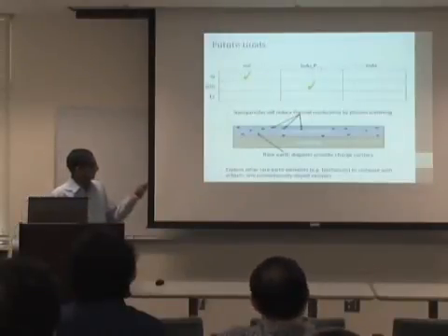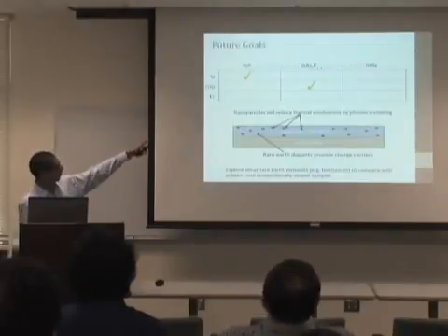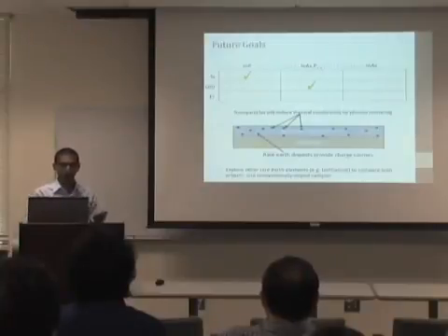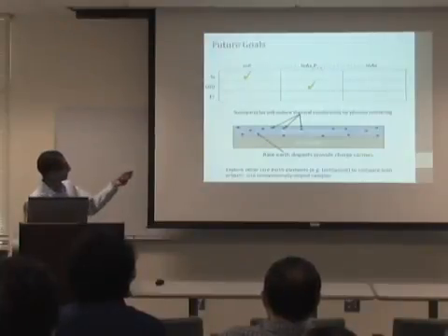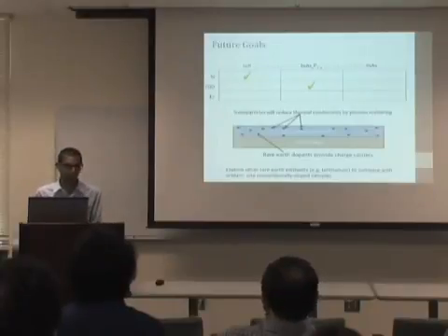So as you can see, this project is still in its early stages. We want to study the entire spectrum, all the way from indium arsenide x phosphide 1 minus x. We'll go x equals 0 all the way to x equals 1. So that's indium phosphide all the way to indium arsenide. And we've done silicon doped, we've done unintentionally doped indium arsenide phosphide. We want to get everything in between here before we start doping with a rare earth to see if that's actually feasible.